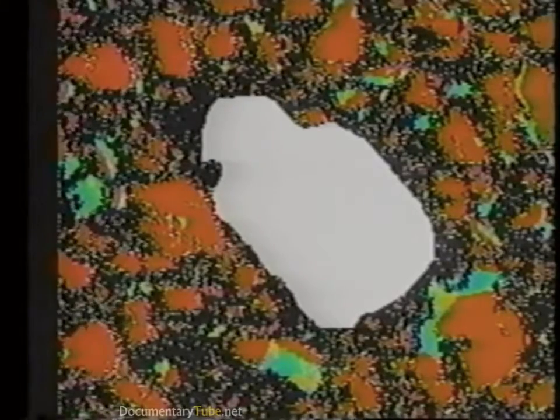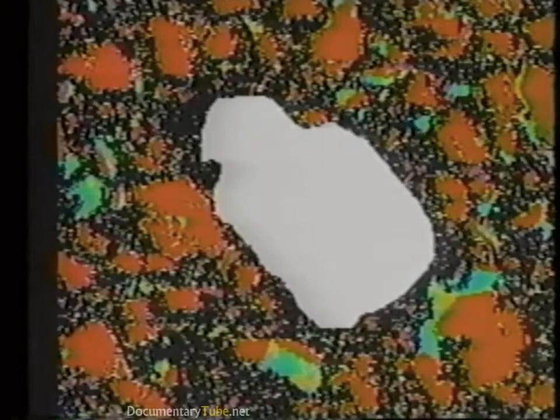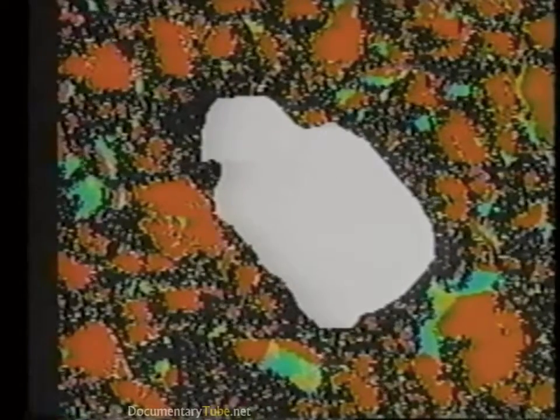The bits of dissolved cement diffuse through the water in a random manner and react to form solid phases according to certain rules. After a cycle of dissolution, diffusion, and precipitation is complete, the computer proceeds with another cycle. As this process repeats again and again, the microstructure develops, building bridges between particles that provide strength to the material.